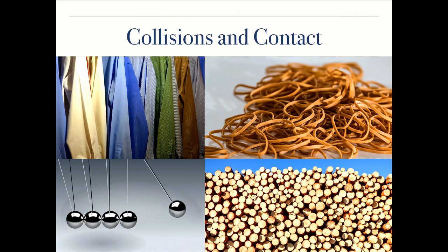So to get a pile like this correct with your simulator, where you've resolved all these contacts, is quite challenging. And generally speaking, contact and collisions and constraints are one of the more difficult parts of a simulation. Just doing F equals ma is relatively easy, but getting all of those constraints, contacts, and collisions resolved makes it much harder.